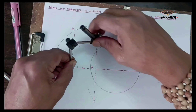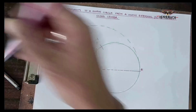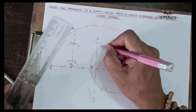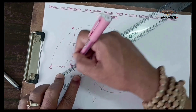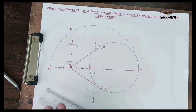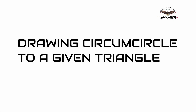Using P as center and PQ as radius, draw two arcs to cut the given circle and name the points R and T. Now join PR and PT, which are the two tangents drawn from external point P to the given circle.